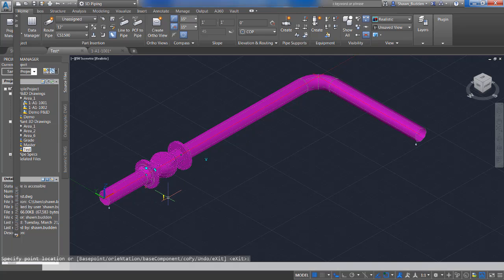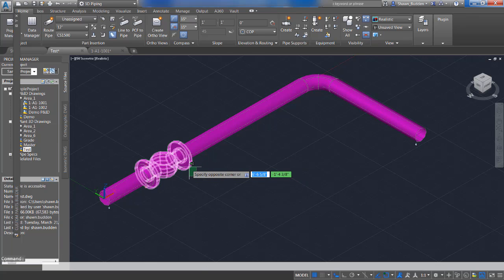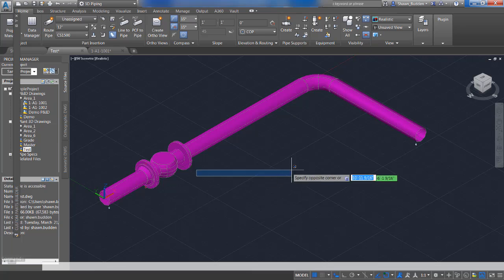You have the little yellow exclamation point right here, and this is telling you that this is a placeholder part. And in the future, if you need to switch it out, you can also use your substitution. If you have any other valves in this family in your spec, then you'll be able to switch those out. So that's just a little bit on how you can actually build a part in your custom parts builder and then insert it into the model.